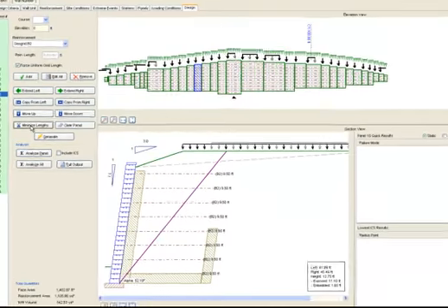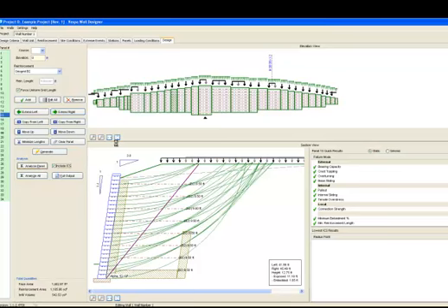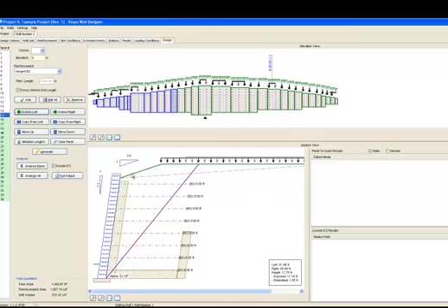This new grid length has to then be checked. Hit Analyze Panel. It appears the minimized lengths are satisfactory. Now run the ICS on this panel only. It appears the ICS analysis is also satisfactory. We can now extend the new grid length left of this panel and continue this process for all panels on the wall. Note that when the grids are extended left, they are turned blue again in the elevation view, meaning you have changed the grid design since the last time we ran the Analyze All button, and they have to be checked again. I will quickly go through and design the wall to ensure all panels meet the minimum criteria.